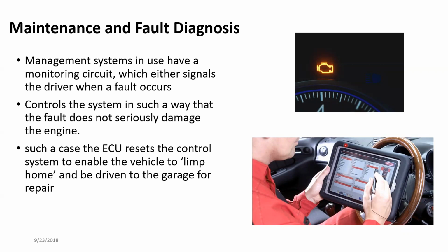let's say engine RPM, you got engine load saying 100% and the engine RPM is 300. What you're reading is 300 engine RPM, but engine load is saying 100%. That's not possible. So at that particular time, the engine actually has to recheck everything. While it is rechecking, it's actually storing this particular problem in the system.